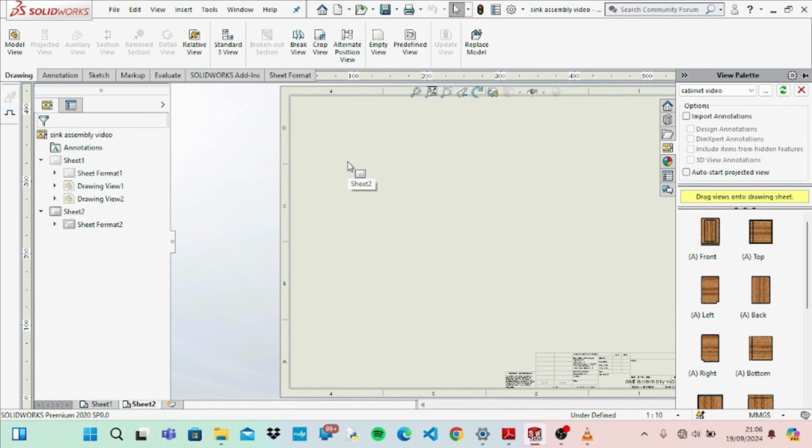In first angle projection, the front view is displayed on the upper left, and in third angle projection, the front view is displayed at the lower left. In SolidWorks, this drawing uses first angle projection.